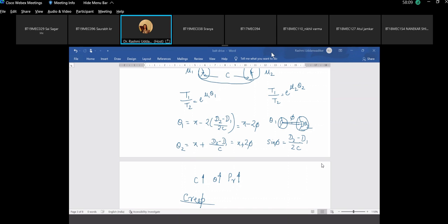This is not creep. You are defining creep with time, which happens in, say, a turbine blade. Continuous loading for a long time leads to deformation, but creep in belt is different. It is irregular expansion and contraction of the belt. Near the pulley, the belt is getting stretched, and then here it is getting compressed.